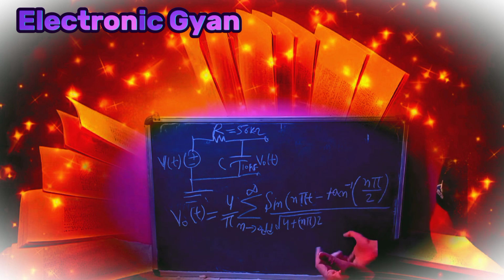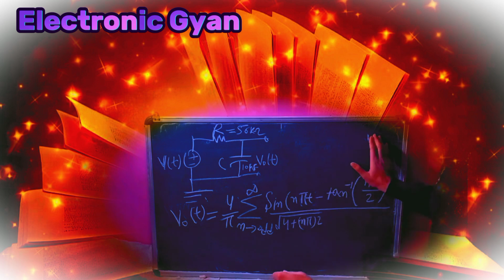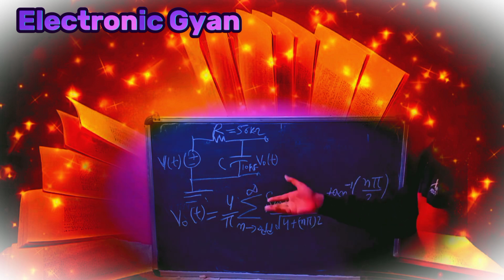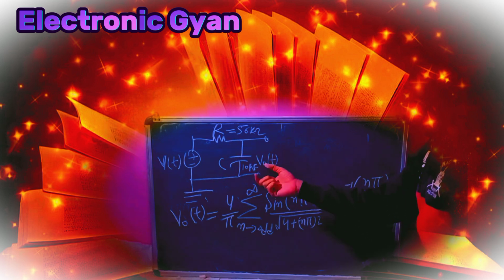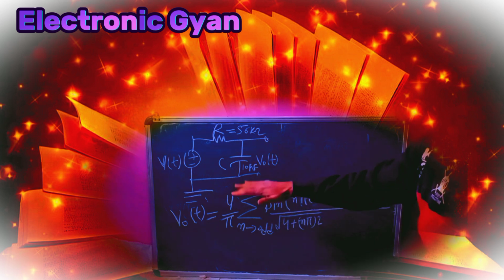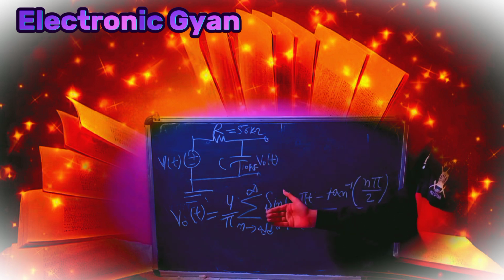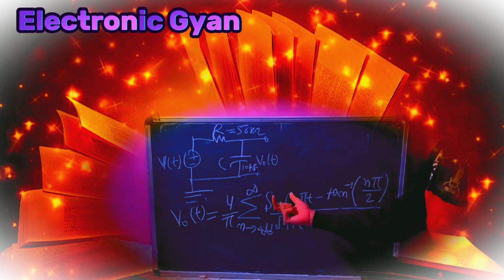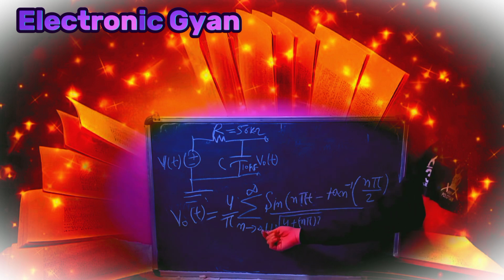This concept we have explained and seen very well. Whenever there is periodic switching in the circuit from the DC supply voltage, it will generate a periodic square wave pulse. So for that we replace that source by a periodic square wave pulse. Then we found the Fourier series expression for that periodic pulse, in the form of sinusoidal and harmonic functions, which are odd harmonics.